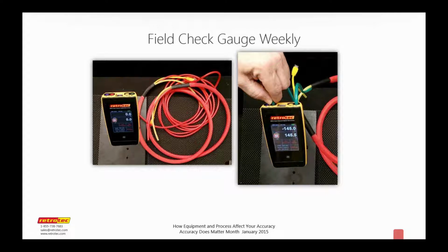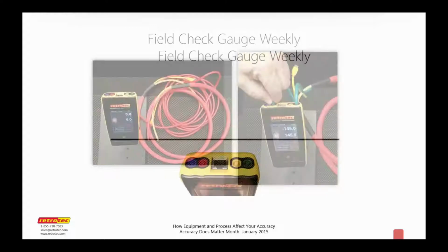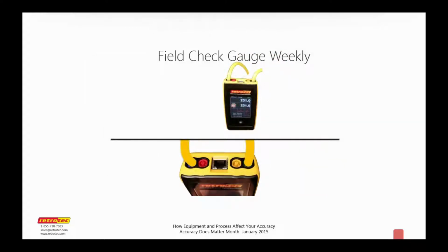So what you want to do is connect a red tube between the red and the yellow ports, and connect your green tube or your yellow tube, depending on if you're running a duct tester or a blower. You want to use your tubes and connect them to various ports on the gauge, and I have a slide right here that illustrates that.